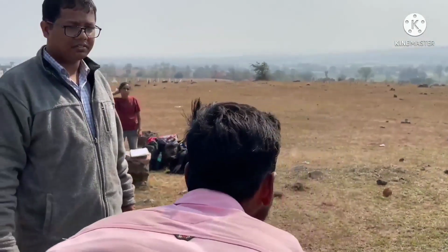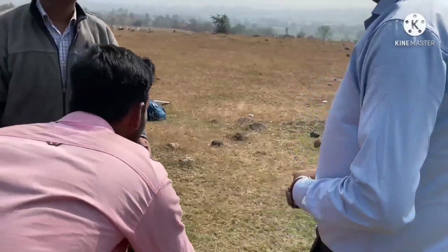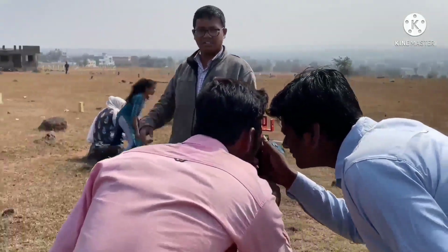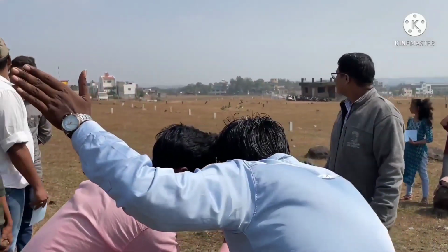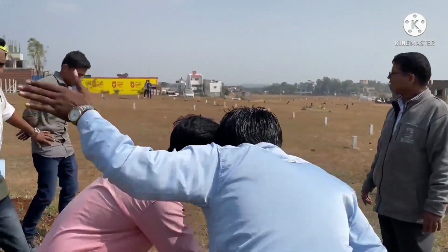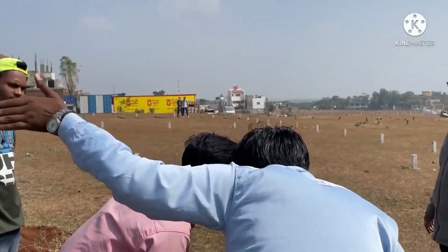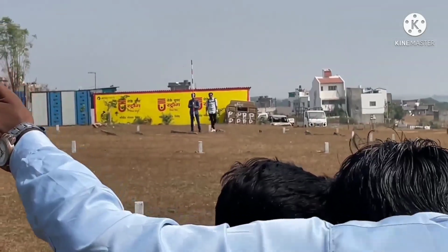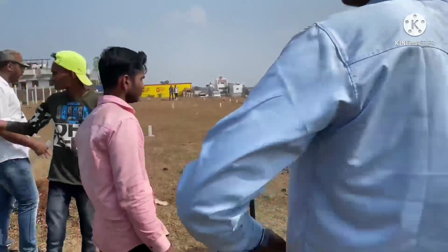Here you can see a person bisecting the ranging rod kept at C100, and a person standing on the other side guiding the person carrying the ranging rod so that it makes an angle of 90 degrees with respect to C100. He is giving sign conventions to move in the left or right direction. Right now it is a 90 degree angle.